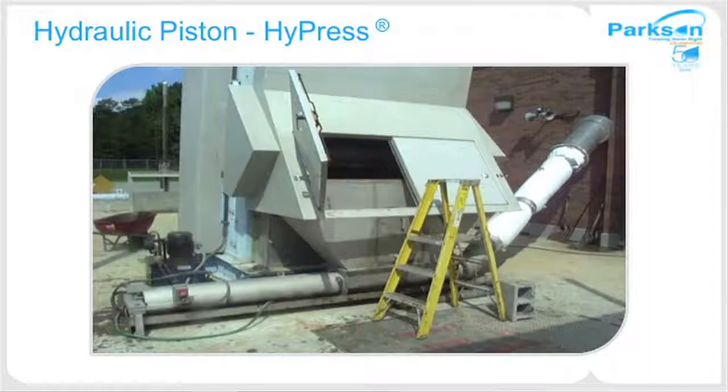And now we are looking at our hydraulic piston HyPress product, which uses a hydraulic piston, or we call it a ram press. There are several names in the industry. It basically pushes the solids further by just using a hydraulic packing gland. And again, the dewatering occurs because of the solids in the pipe, and then the most important feature for this piece of equipment is that you can really push solids far away, up to 30, 40 feet away if you need to.